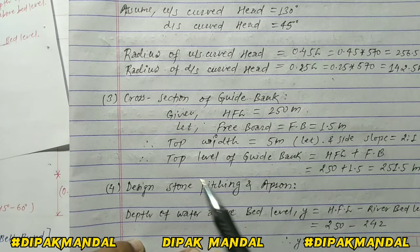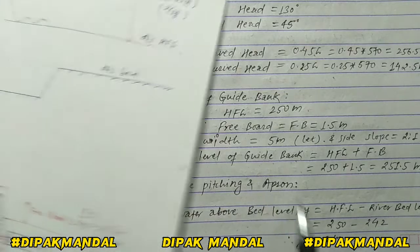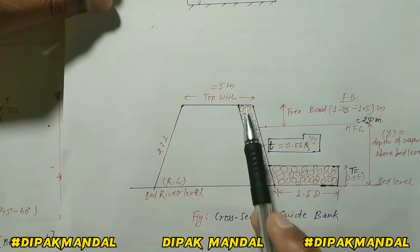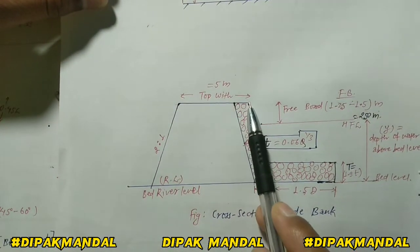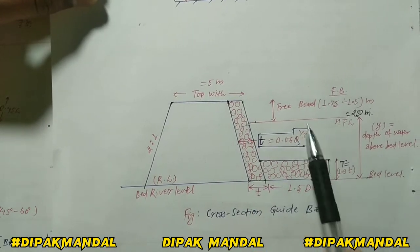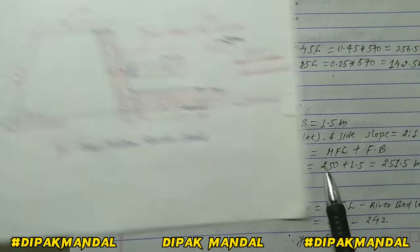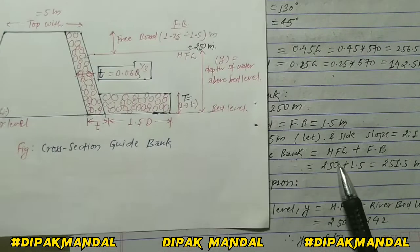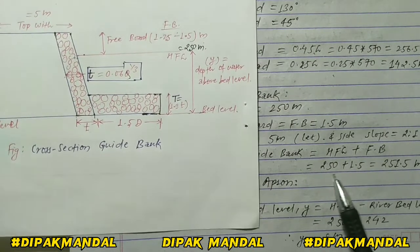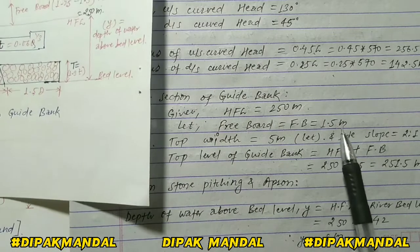Now we have to calculate the top level of guide bank. Simply, you can calculate this top level of guide bank by adding the freeboard to the HFL. The value of HFL is given in the question, 250, plus freeboard, which we have already assumed as 1.5 meter.